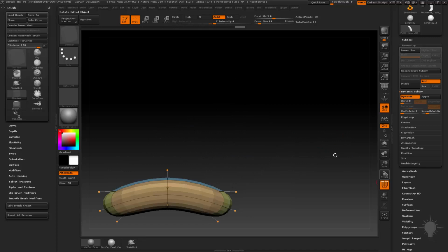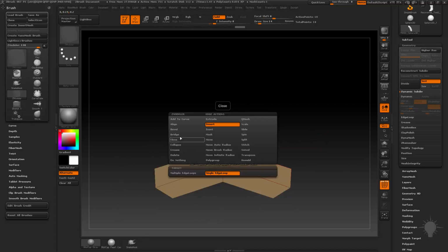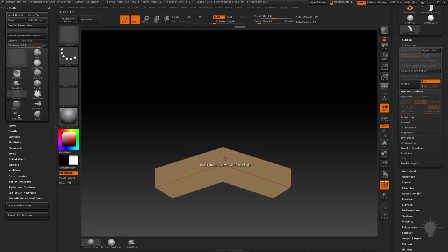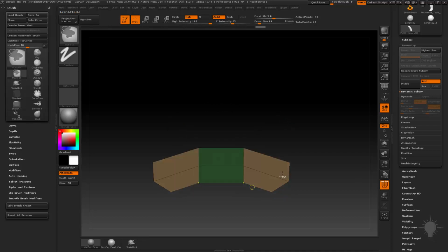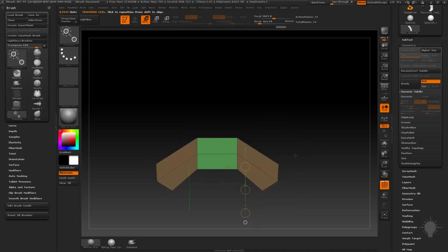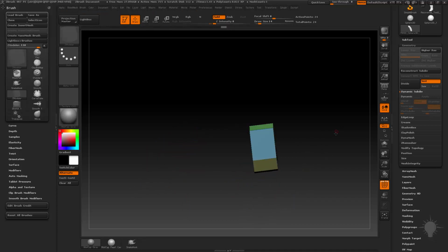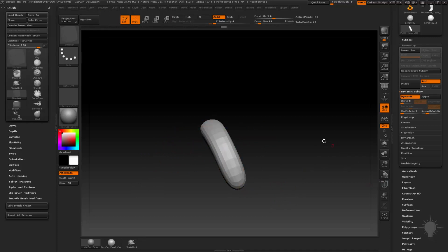If you want to give it a little bit more bend, let's go ahead and take this line here, and instead of insert, I'm going to do bevel edge loop complete, and I'm just going to bevel that edge down, and I'm going to Control drag those, Control tap to invert, W, and then just move those up. And then I'll rotate these around a little bit more. There we go, a little bit more of an arch. So there's our first stitch.